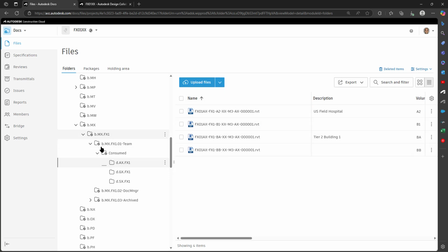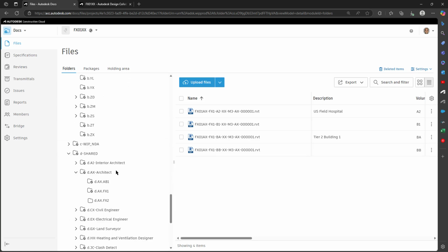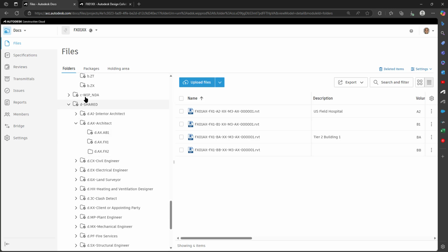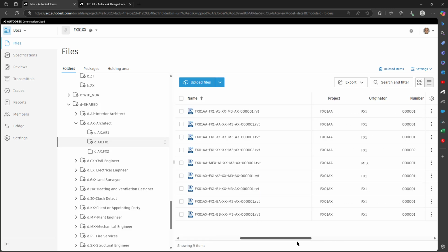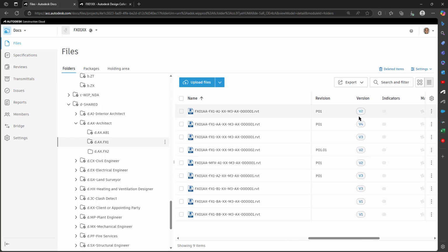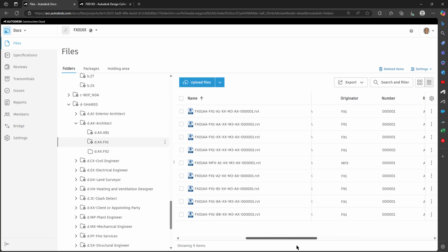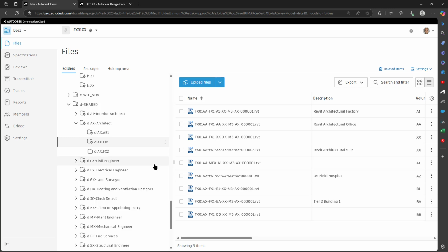In other words, you've got control of these files. That is not a problem, because if we ever have to compare files, if something went wrong, we would always refer to what we call the one version of the truth, which is the record that is kept within a shared folder, and it is versioned as you would update that file. So there you can see there are various versions, and these versions can be slip sheeted. That means it could be rolled back to an earlier version if necessary, and the metadata that is associated with that would also change accordingly. So that, in short, is the BIM level 2 compliancy that we are talking about.